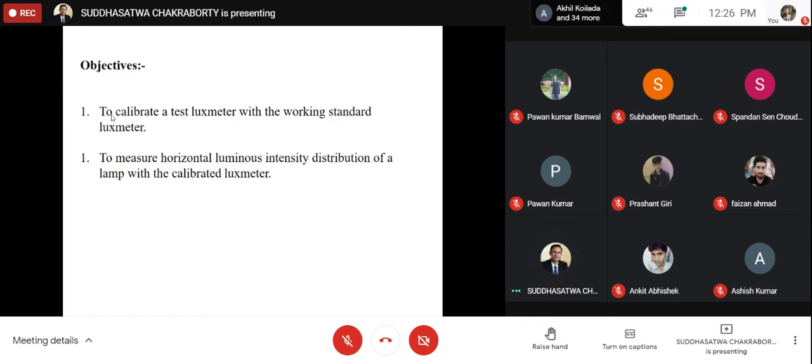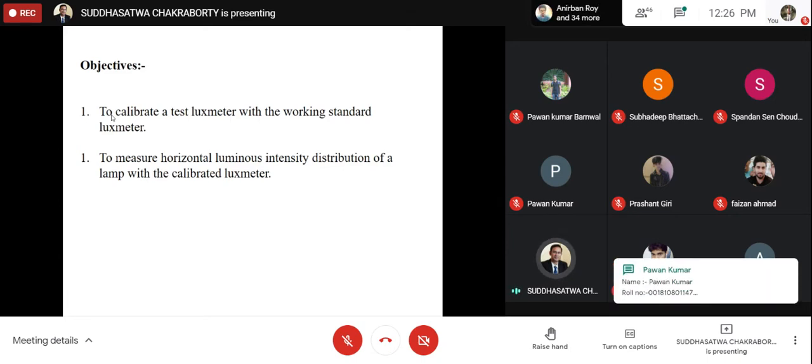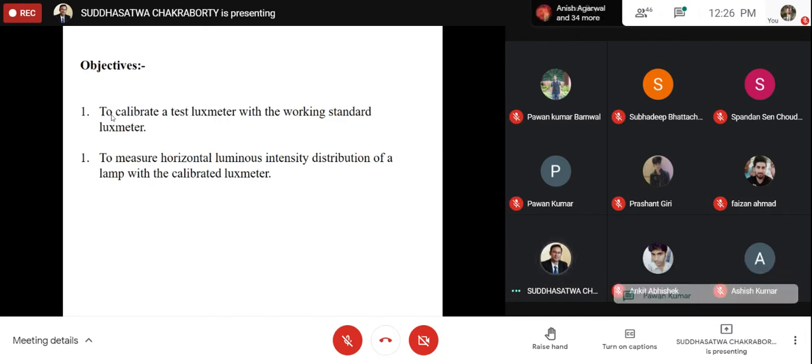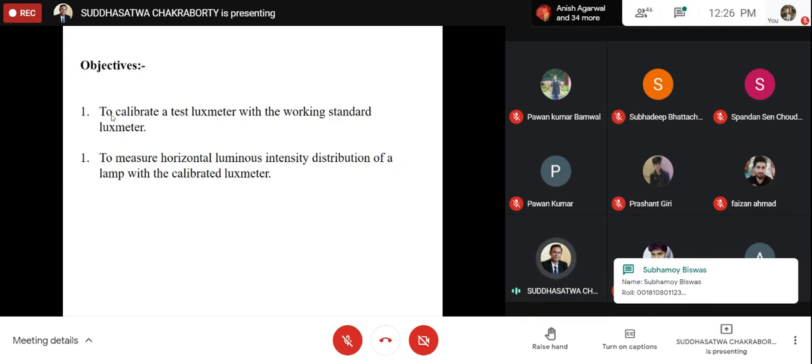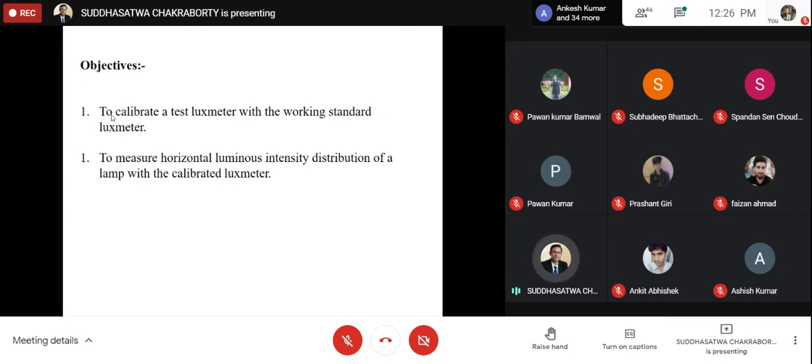Sometimes we directly start measuring using the instrument, but that will not help us, otherwise we will never be able to say whether our measured data are erroneous or not. So calibration is not a separate part of our measurement; it is an already integrated part of all measuring steps.